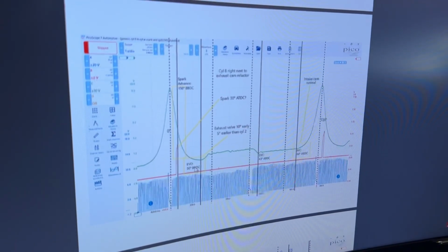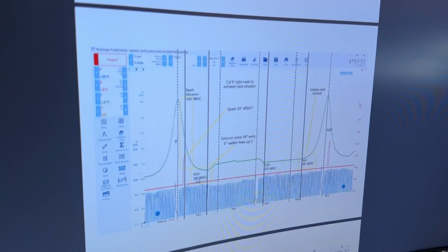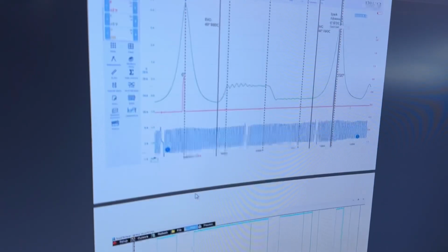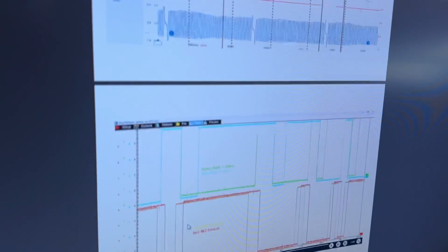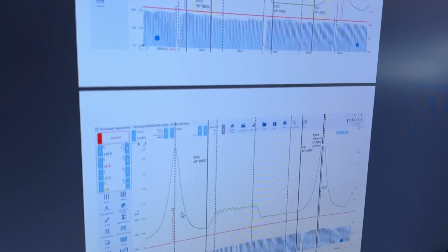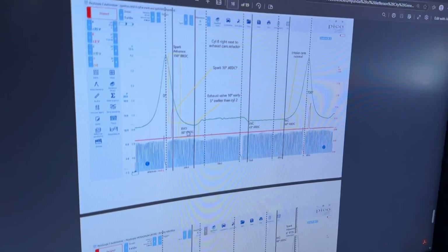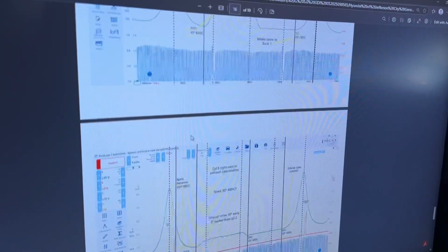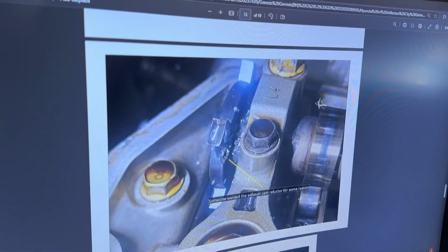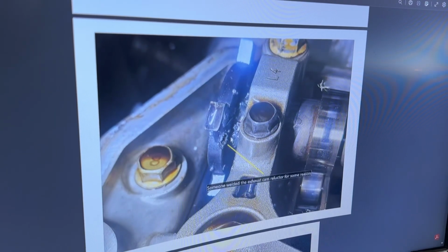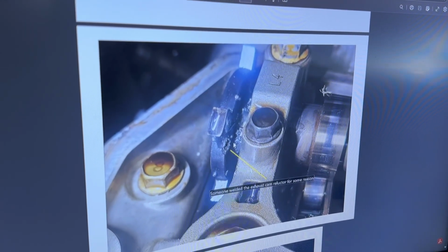Here's what's interesting, all right? This one's early. However, this one's late. So how can our camshaft be late as far as the sensor's concerned, but yet as far as our in-cylinder is concerned, our cam timing is early, 10 degrees early, actually. Well, let me show you how. Somebody had a welder. So basically, I suspect that this vehicle has an issue with the cam phaser on the exhaust cam on bank 2.